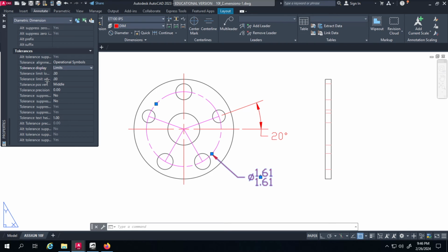So precision tolerance, for kicks, I'll change that to 3 places. I don't remember what the directions were. And then you can add your upper and lower tolerance. For example, if I say .02 for upper, you'll notice that this changes. Watch this change to add the .02 as soon as I hit tab to accept that. Oh, sorry, this is the lower one here. I changed the lower one, .02. I'll change this one to .01 and hit tab, and you saw that change to one place. All right, hope that helps complete this demo.